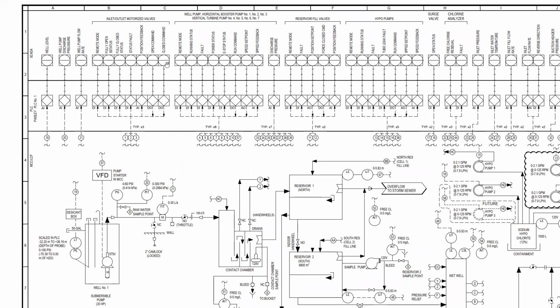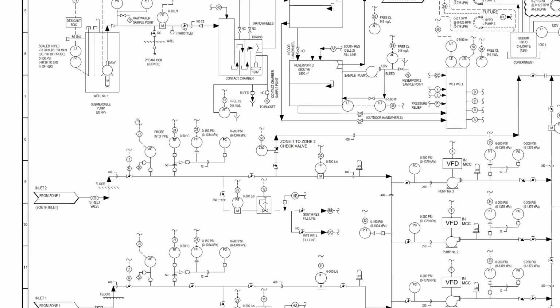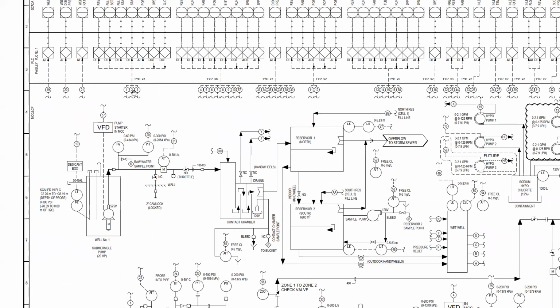And because this is only 75% design, we hadn't had a chance to fill in some of these blocks with data tags. So the 100% or the as-built drawings will have the DI/DO, and the remote status tags and the device tags will get filled in later. So we can see here that 1 and 2, these bubbles come up and line up with 1 and 2.